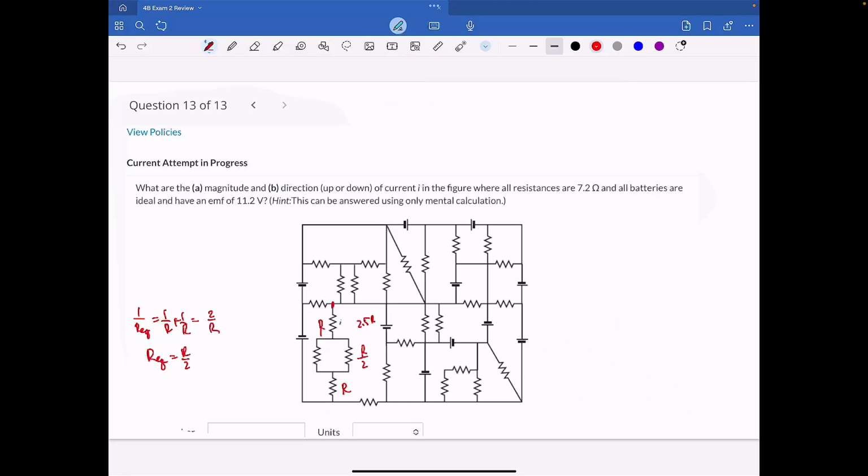That leaves the path to take through this circuit. I'm going to start here and go down. Now I'm just doing a loop rule, a Kirchhoff's loop rule, through this circuit. Going down, I know I have to go along that path because it contains the current I want to find. But do I want to do any other currents in any other junctions? No. Follow my loop around. What's interesting about Kirchhoff's loop rule is that you don't need to know the current if you're moving through what? Batteries, voltage sources. So let's avoid every branch that has a resistor from here on out.